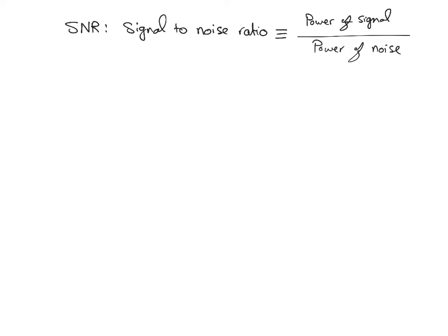Okay, so if I know the average power that I send my signal with, and I know the average noise power at the receiver side, I can calculate the SNR, and if I know the channel bandwidth, I can calculate the capacity of the channel. Now this equation adds one more parameter to the things that you trade off over the channel, right? Remember, we said that you trade off probability of error with bandwidth or rate. Also, you can trade off probability of error with power, or rate with power. So there are three parameters.